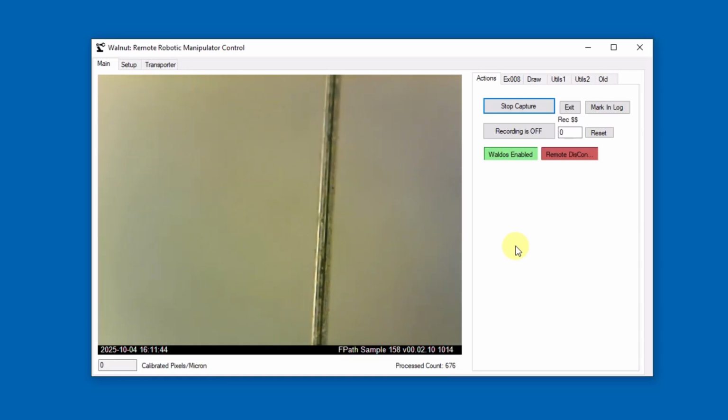Measuring it with a good set of calipers indicates it is actually 0.09 of a millimeter, or 90 microns in size. Moving the wire to as vertical a position as possible, I can click on each side with the mouse. I don't need to place red lines here. I could if I wanted to, but the mouse clicks are recorded anyway.